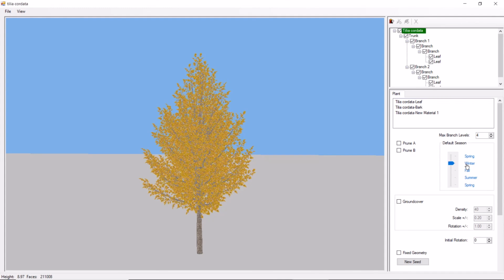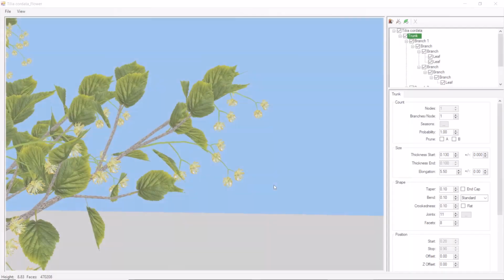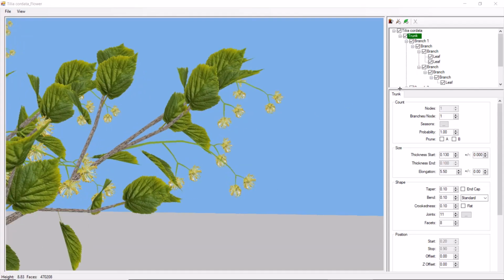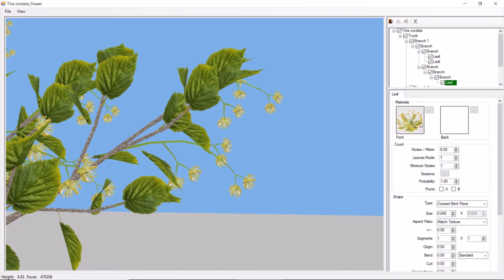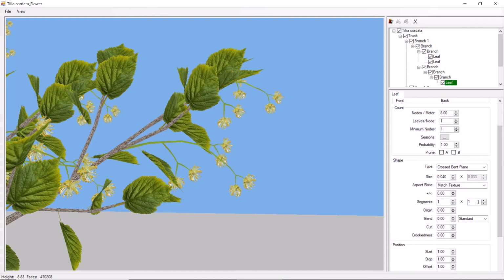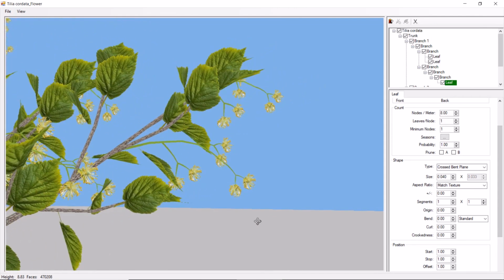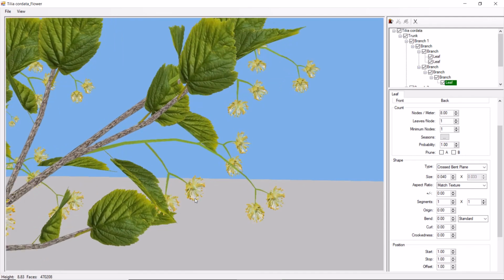We can also use the leaf component to create flowers, fruits, or different elements. In this file, I have created a couple more branches to distribute the flowers. One of the options we have, as you can see here, is to use a centered image of the complete flower as a texture and use the option Mesh Plane. With the segments set to 1 and without any curvature, we would generate this volumetric appearance. This resource is the most suitable for representing small details and minimizing the number of faces, as in this case.